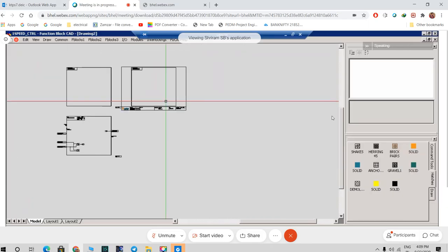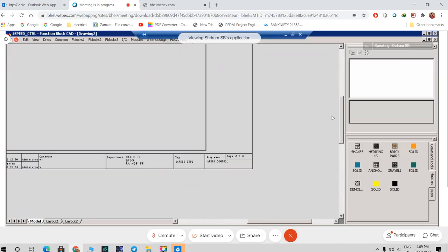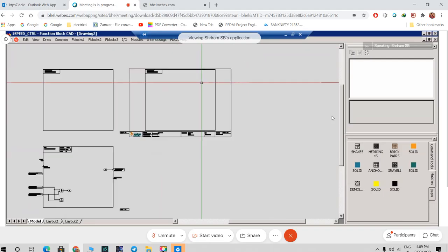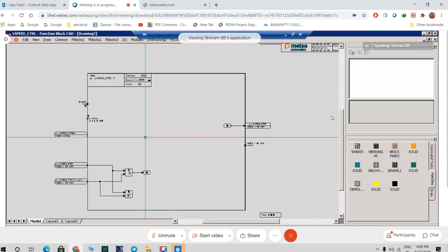And one thing we have to remember is that whenever you are creating logic, the system is thinking we are in page 3 because page 3 is what is selected. Suppose you just zoom out directly and do some logic here, you add some blocks here. Then those blocks will automatically get assigned to page 3. So when you are compiling, the system will throw an error saying you have assigned blocks for page 3, but you have put them in page 1 borders or wherever.